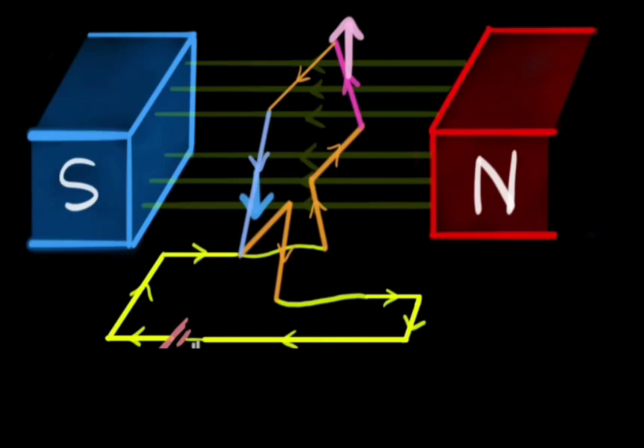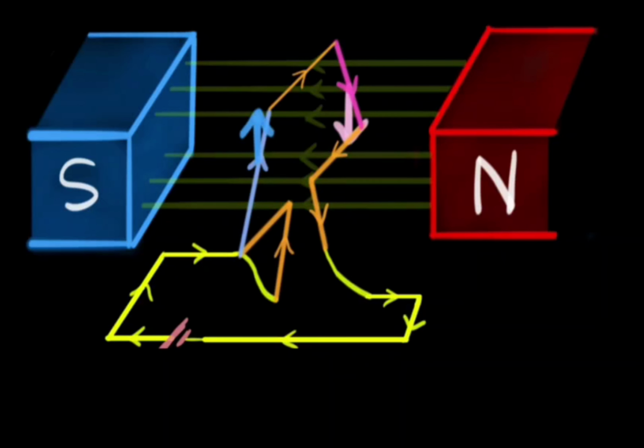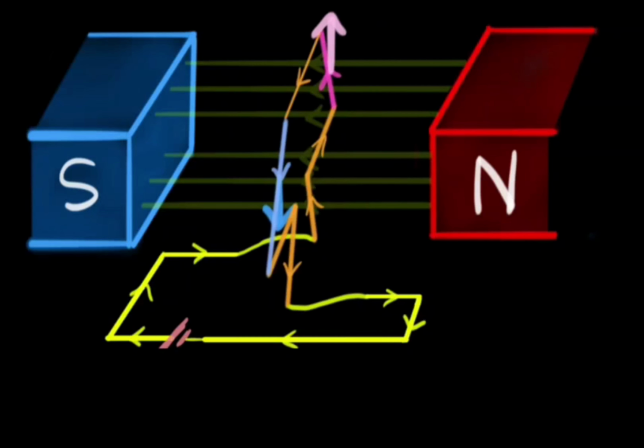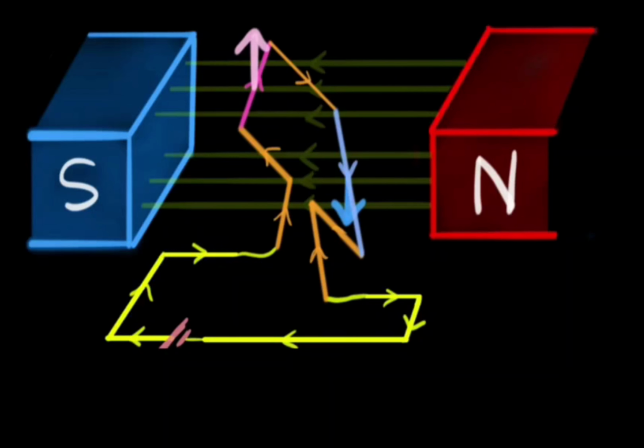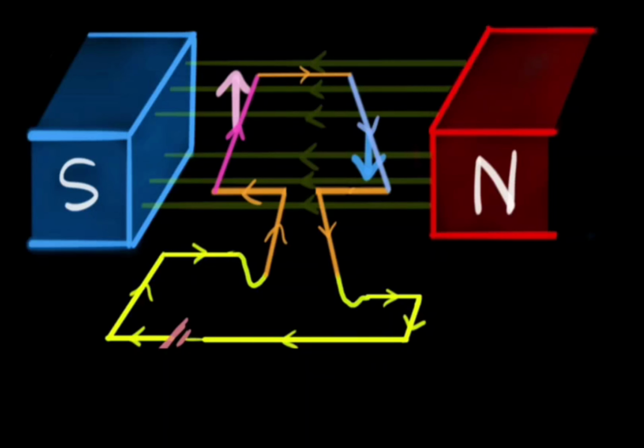It is important in the case of the motor to appreciate that this is proportional to the product of the flux and the speed. Thus, with EB denoting the back EMF, phi the flux and n the speed, it may be written as EB equals K phi n, where K is a constant depending on the nature of the armature windings.